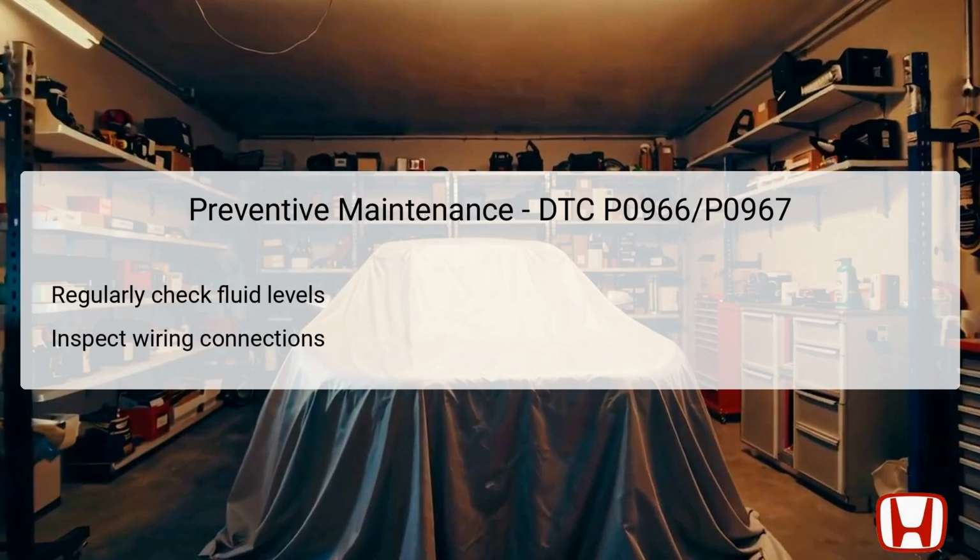Additionally, inspect wiring connections periodically, especially around the components related to the CVT, to detect any signs of wear or corrosion that could lead to electrical faults. Maintaining the cleanliness of the wiring harness and ensuring that no loose connections exist will go a long way in preventing future diagnostic trouble codes from being triggered. Such preventive measures are critical in prolonging the lifespan of the transmission system and ensuring optimal vehicle performance.